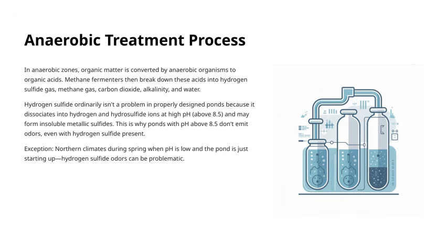However, there's an exception to keep in mind. In northern climates during spring, the pH can be lower, especially when the pond is just starting up. In these conditions, hydrogen sulfide odors can become problematic and may require additional management. So, understanding these processes helps us see why maintaining proper pH levels is crucial in controlling odors and ensuring effective anaerobic treatment.